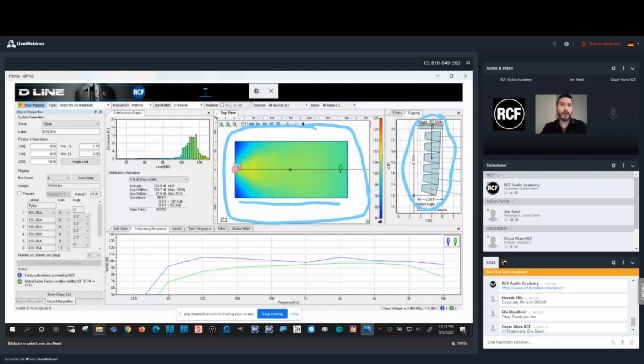Where before we were talking about 100 feet, say 1,000 people in a 100-foot area, now we're talking about, what, 5,000 people in a 300-foot area. Will 6 HDL30s cover this? And the answer is yes. You could see here that the coverage is relatively smooth from the start of the coverage area all the way to the back.